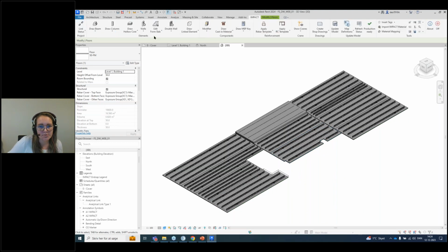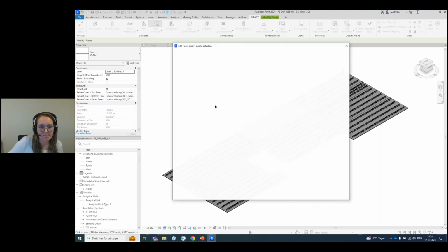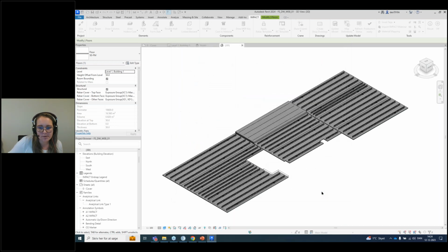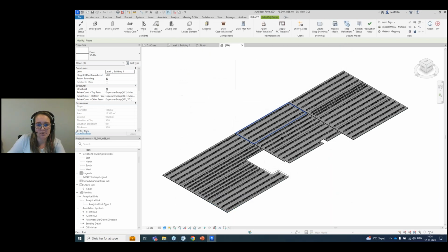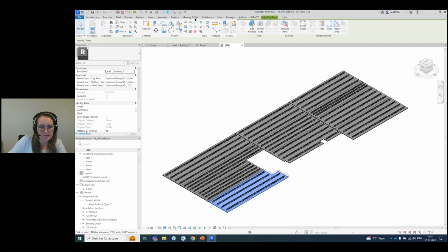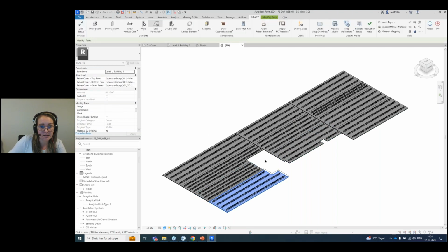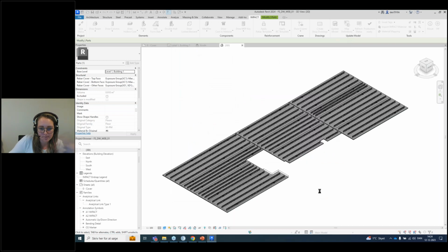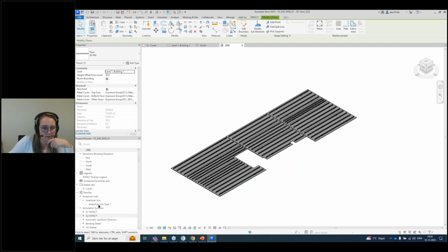So it's a very good way to show it in your model. If you want to remove it, you just uncheck it. It goes back to normal, and the same in here. You need, of course, to select this slab and uncheck show full thickness. So, presentation possibilities, very good if you are modeling here in Revit.